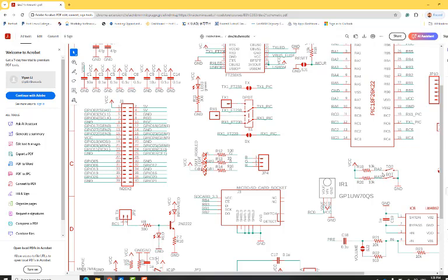Okay. So now let me know why you don't want to use a low value. I know you already answered that question. But if you push it, what's going to happen? Yeah, it closes the circuit, so the only component in the circuit is the resistor. And 5 volts divided by the resistor will be the current. So if the pull-up resistor is like 1 ohm, what's the current running in the circuit? 5 amps. Is that a big current or small current? Yeah, huge.